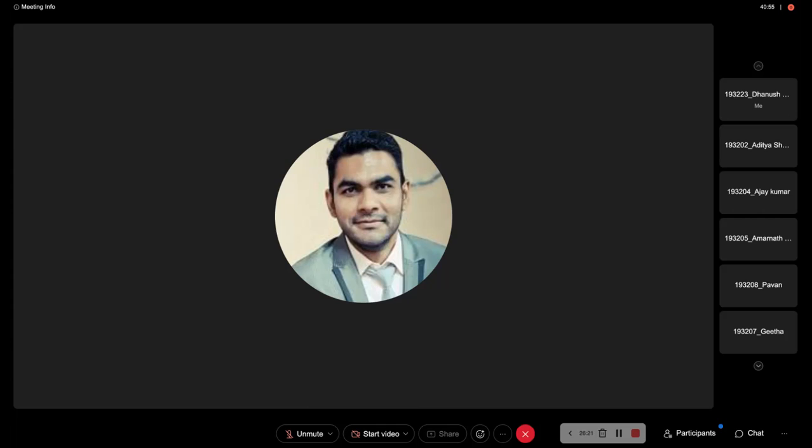Okay. So I1 is equal to I2 plus I3, and I1 can be equal to (V minus VA) upon R. That is, this is junction A. So the potential difference across this resistance will be V minus VA.